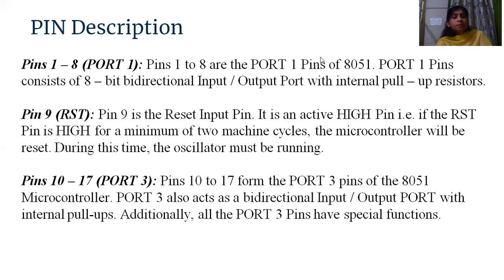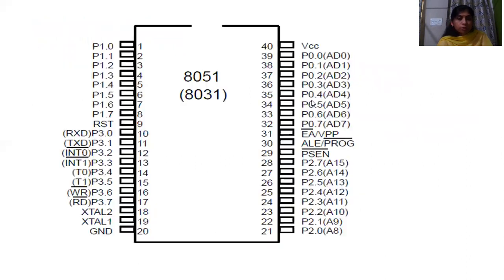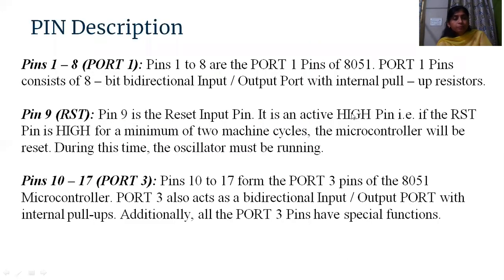Pin number 9 is the reset pin. It is an active high pin. As I have told you, the bar indicates active low pins, and without a bar it is an active high pin. If the reset pin is high for a minimum of 2 machine cycles, the microcontroller will be reset.